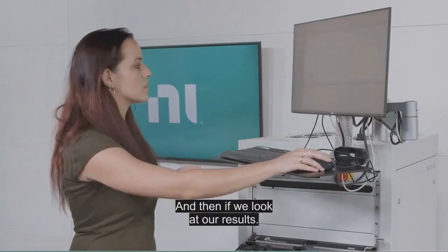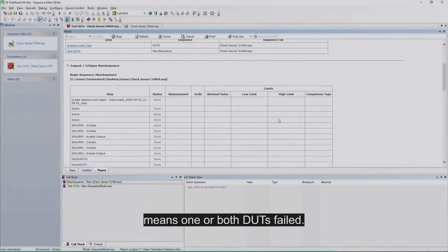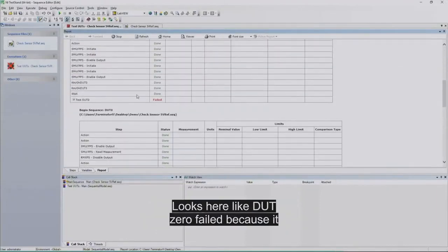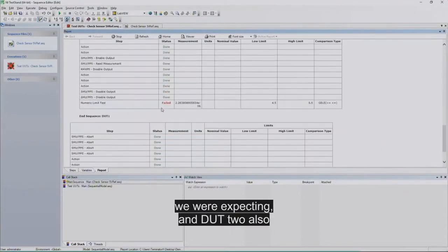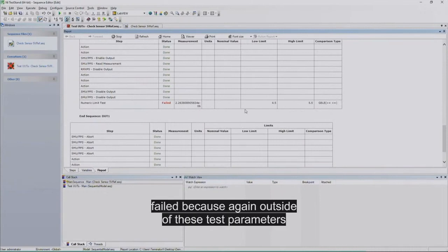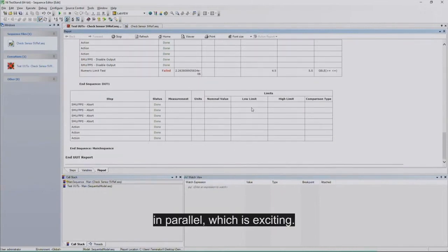And then if we look at our results, you can see here that our test failed overall, which means one or both steps failed. Unit 0 failed because it was getting a much lower signal than the 5 volts we were expecting. And unit 2 also failed because, again, it was outside of the test parameters we defined. Again, as you can see, those are tested in parallel, which is exciting.